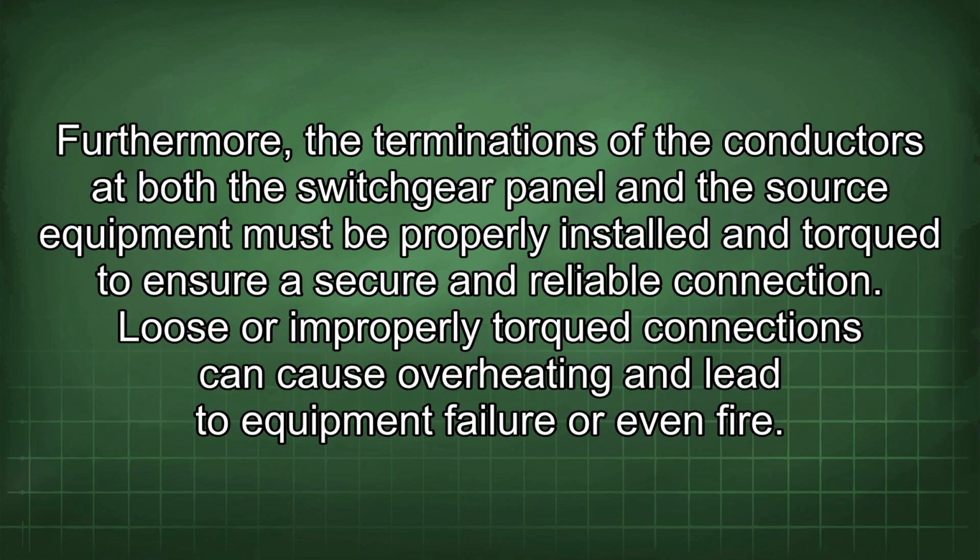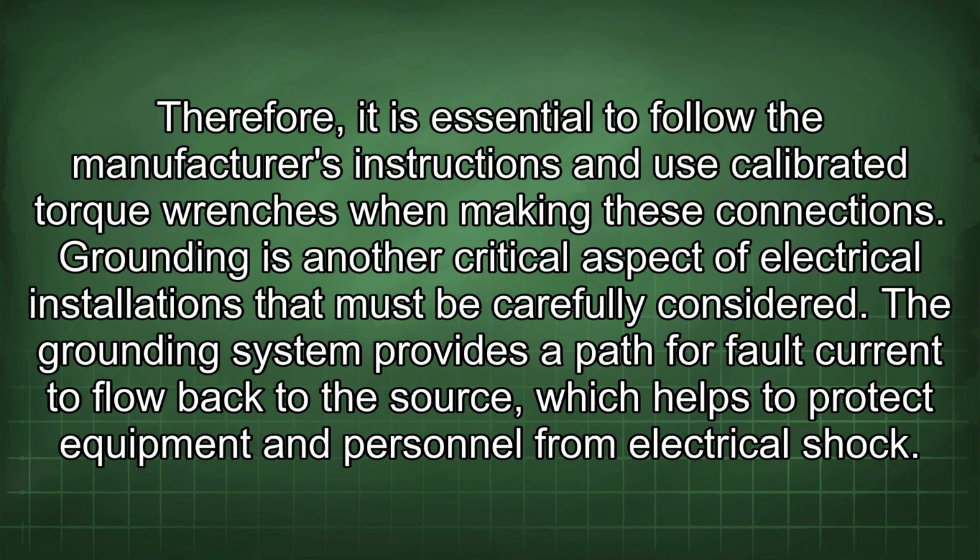Furthermore, the terminations of the conductors at both the switchgear panel and the source equipment must be properly installed and torqued to ensure a secure and reliable connection. Loose or improperly torqued connections can cause overheating and lead to equipment failure or even fire. Therefore, it is essential to follow the manufacturer's instructions and use calibrated torque wrenches when making these connections.